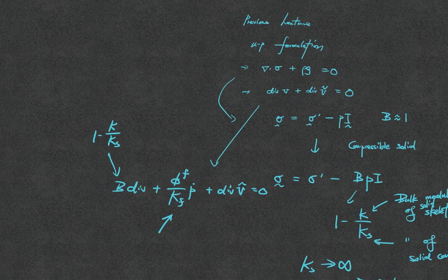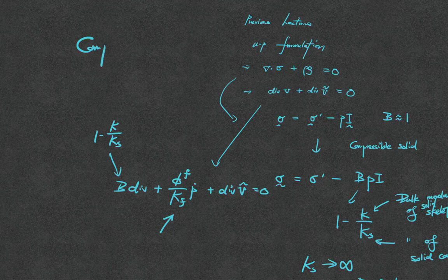Now this is for compressible flow. For water, you may not consider it as compressible unless in some extreme case. I mean, there are always extreme cases. You need to consider extreme high temperature or extreme high pressure, then the general assumption of incompressibility may not hold, or you simply deal with gas, or something that is lighter, then you cannot assume the material is incompressible.